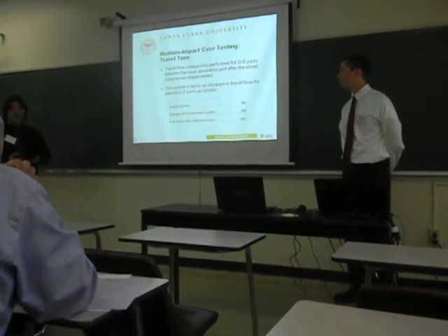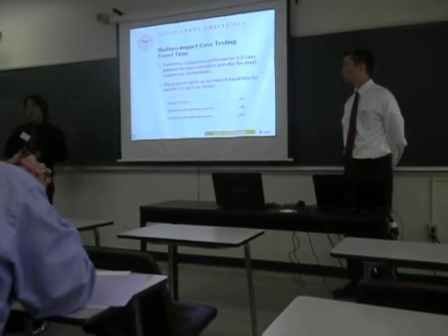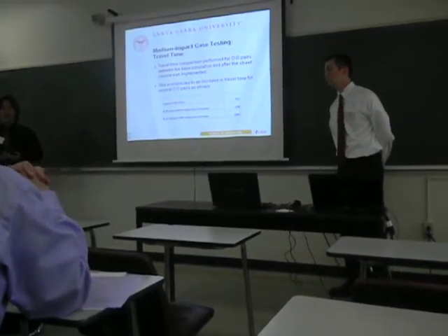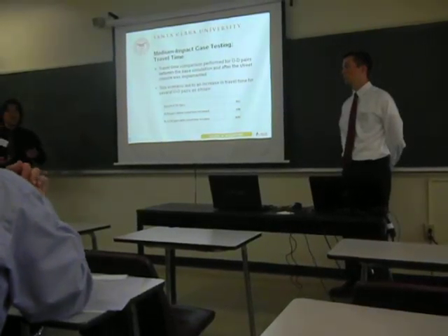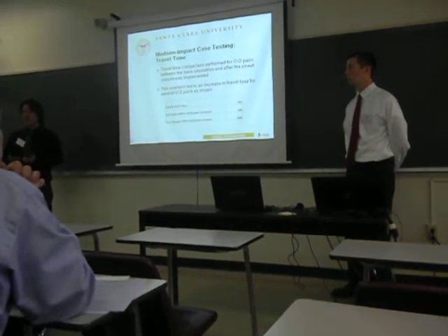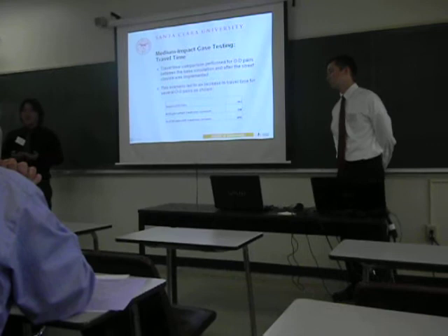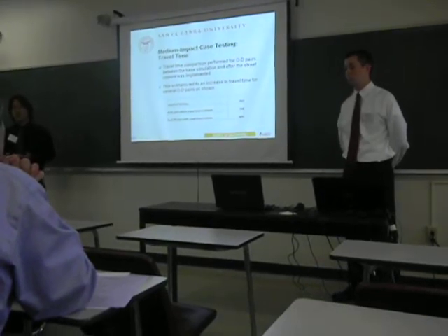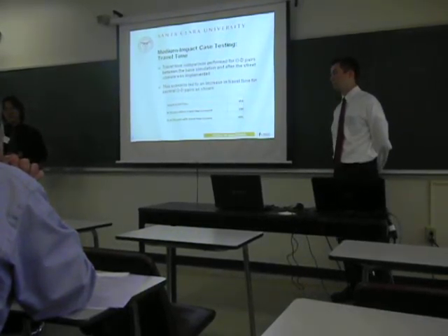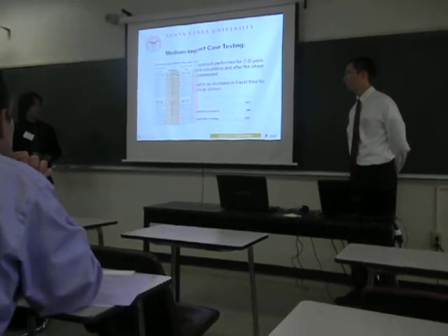One of the analyses we did was a travel time analysis. We looked at all of the origin-destination pairs in our system, and after we implemented the street closure, we looked at how many of these OD pairs had an increase in travel time. As you can see from this table, there was a 30% increase in the number of OD pairs that had an increase in travel time, therefore showing that this street closure is indeed affecting our system.